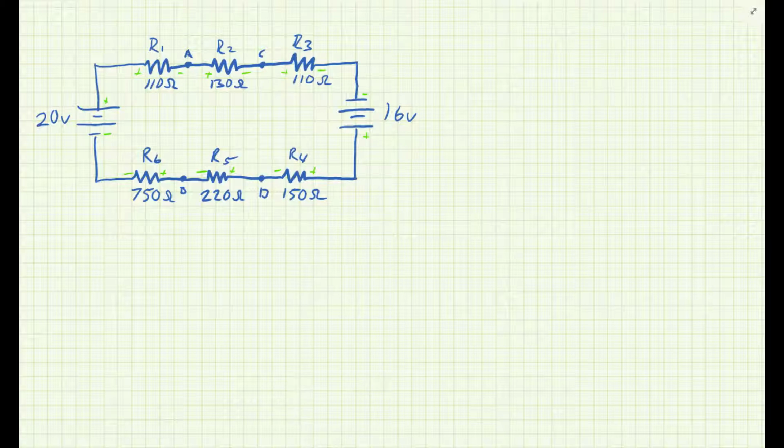So I'm just going to draw a quick Kirchhoff voltage loop equation just to see how this goes. So Kirchhoff says, and I'll just start here in my traditional bottom left hand corner, go clockwise as I always do, 0 volts in any closed loop equals the sum of all voltages around that loop. Okay, so let's just look at what all that might look like. So I'm just going to go from this point clockwise, and I will end on that point.